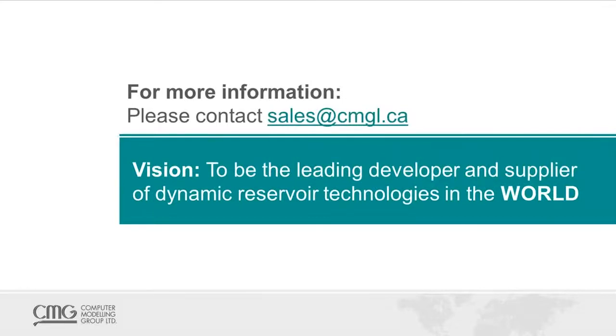The next question is again from Kushagra Saxena. Can we do rel-perm interpolation based on two or more interpolants? Example, salt concentration or IFT or asphaltene precipitation at the same time? Yes, actually you can do the interpolation, or you can consider the effect of, for example, IFT and hysteresis on the relative permeability curves. Yes, you can.